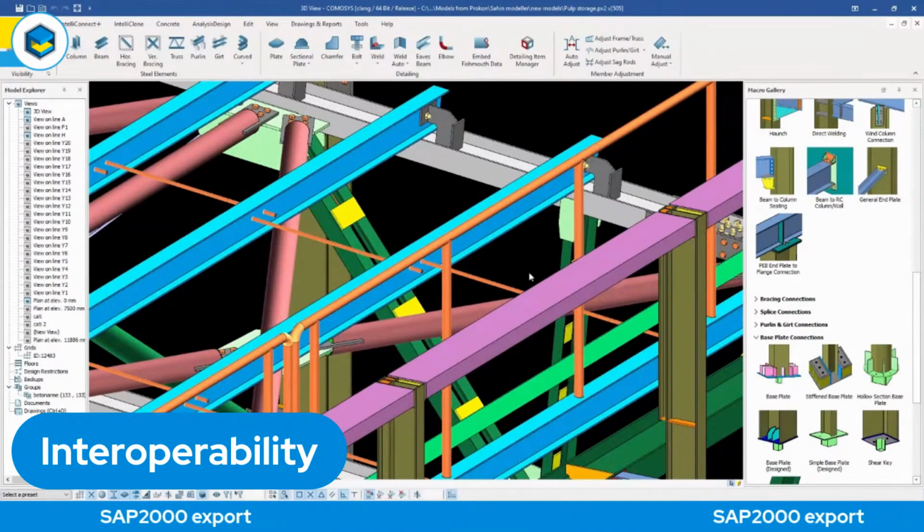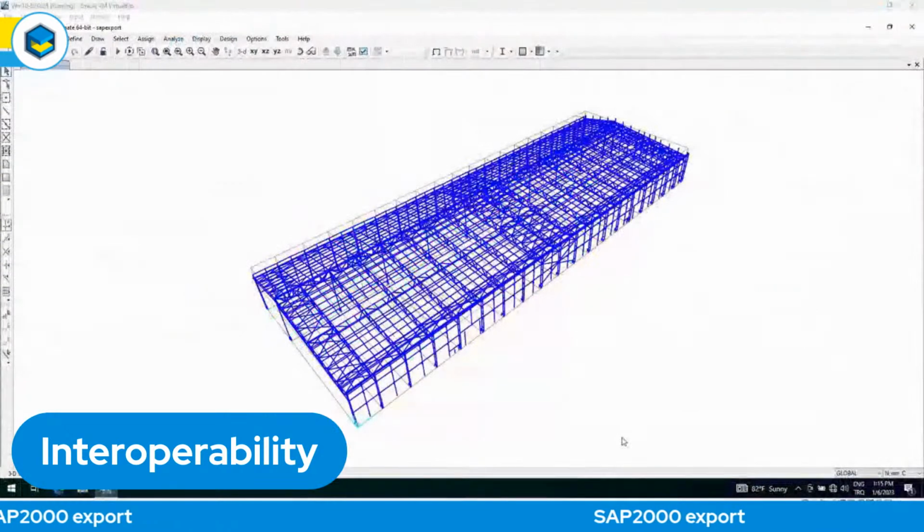The only thing they need to do is that inside the S2K file, there is a reference to the PRO file, which is the section parameters, and there's a local path. So this local path is basically dependent on your machine. If you're giving it to someone else to use, then you need to change the path of the PRO file given in the S2K. This is a simple find and replace command. You just look for all the instances where the PRO file has been mentioned, and then quickly find and replace with the new path, and you will be able to use it.